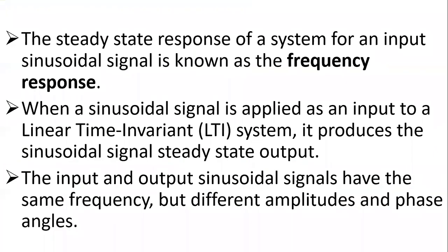The steady state response of a system for an input sinusoidal signal is known as the frequency response. When a sinusoidal signal is applied as an input to a linear time invariant system, it produces a steady state output, which is also a sinusoidal signal. Input and output sinusoidal signals have the same frequency, but different amplitudes and phase angles.